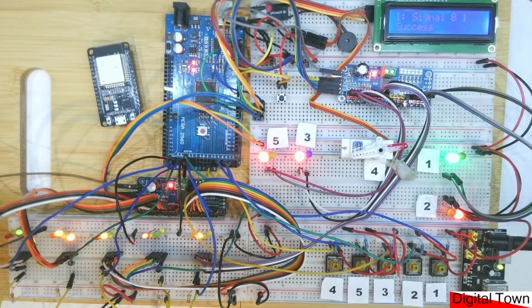You can add virtual signals into the new system to allow for it to actually be monitoring signals that don't actually exist in reality. So that is how the block signaling works. And if I had a second train that had come up into this other block, as you can see, I get a red signal because this train is now in the block, but this driver would now be approaching a single yellow, and after that he's going to have a red because the next block obviously is occupied.